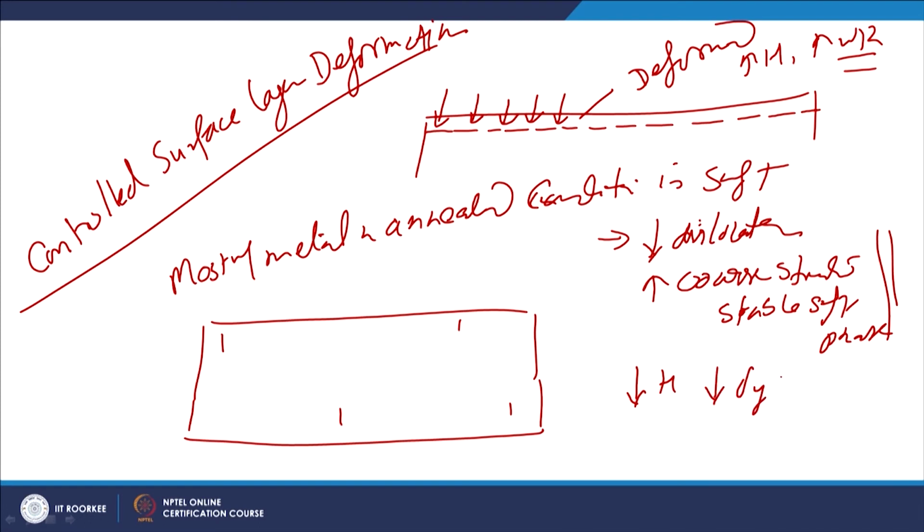yield strength, and therefore, by mechanical deformation or plastic deformation using mechanical force, if we increase the number of dislocations in the metal which is being considered, then it will simply increase the yield strength of the material, because according to the dislocation theory, deformation is facilitated through the movement of these dislocations, and when we have a large number of dislocations, then resistance to the movement of these dislocations increases, and therefore, resistance to plastic deformation is also enhanced.